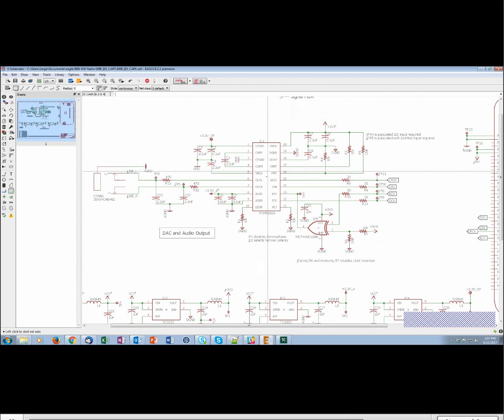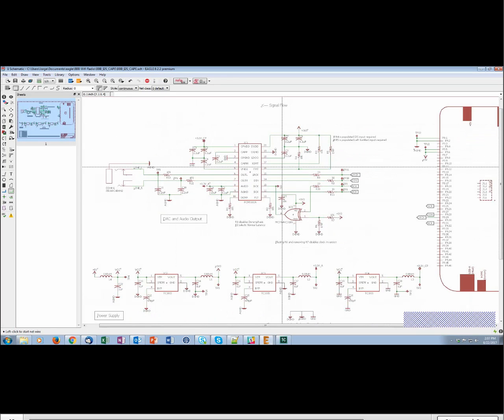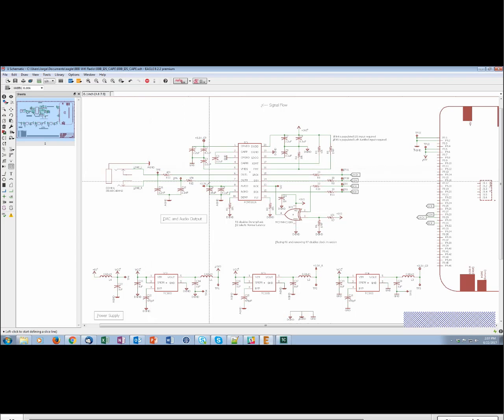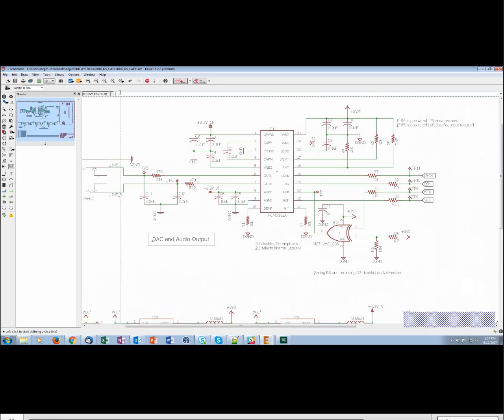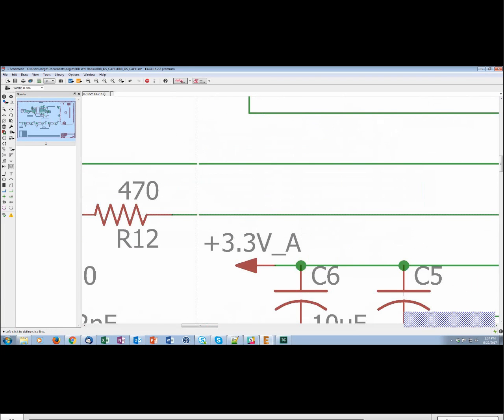So next, we're going to talk about slicing. Slicing is an interesting feature. If we look, it's over here. It's available on both the schematic and the board. And what it allows us to do is to create a break in either a net or a trace. So for example, you can enter a specific breaking line in the command line, so you can enter points for the line to cross through, or you can just left click to start and left click again, and you'll see that it creates a separation. That separation is controlled by this width parameter, and I can just do Control Z to undo it.